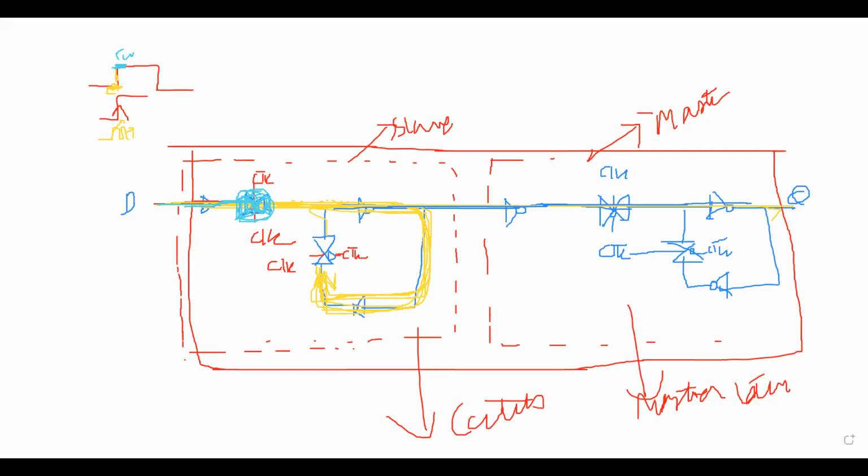Sir, in an interview, if someone asks this question, how can we tell them instantly, because we do not have time to draw this circuit? You can just say that setup time is the minimum amount of time for which the data should be stable before any clock edge, so that it does not go into metastability. I've just drawn this for your explanation.